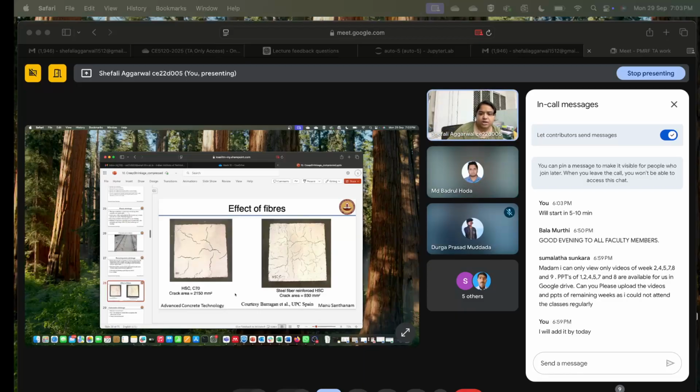Before, from the initial itself. If we talk about shrinkage only, your plastic shrinkage will reduce because of addition of fibers. It will hold your concrete closed, keep your concrete in a compact way. It will avoid crack from expanding. So from the initial stage itself, your plastic crack will be much lower when you are adding fibers as compared to without fibers. So mainly in the plastic stage also your fibers will be helpful. Okay, okay. Thank you.